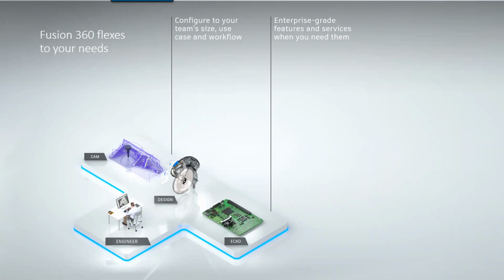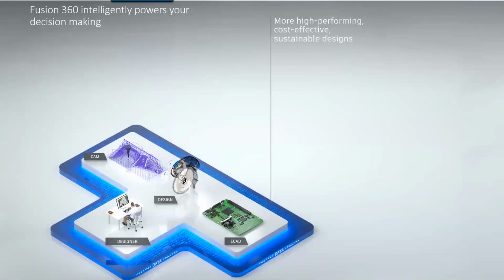Once you get that portion created or laid out, you're going to want to design some sort of enclosure, maybe a mount, design that inside of Fusion 360, and without even having to leave the software, you can manufacture those parts and then create toolpaths that are ultimately going to run your CNC machine. So again, this is a platform that your everyday designer and engineer can take advantage of and really leverage the functionality and the different features that are built into that software.